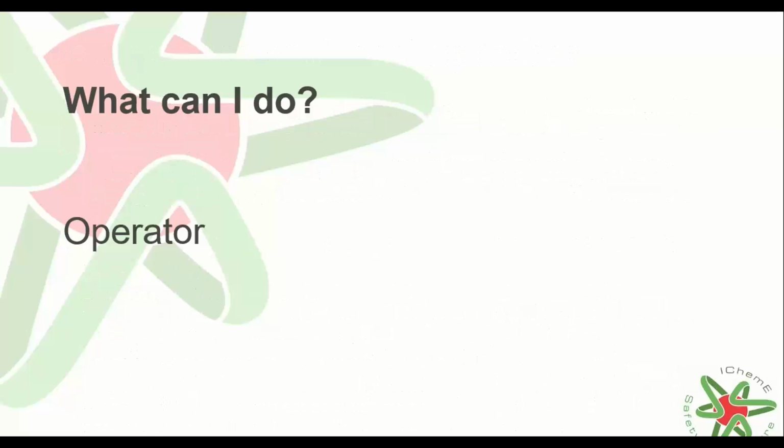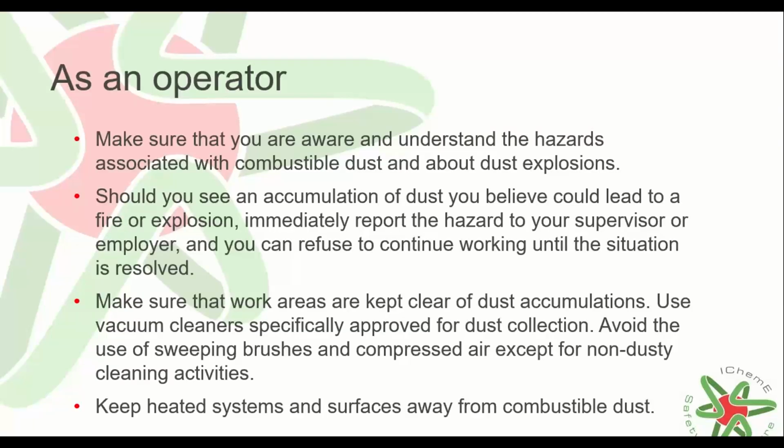I also collected some information about what, as an operator, I can do about dust explosions, and there are a couple of those here. As an operator, make sure that you are aware and understand the hazards associated with combustible dust and dust explosions. And should you see an accumulation of dust that you believe could lead to a fire or explosion, immediately report the hazard to your supervisor or employer, and refuse to continue working until the situation is resolved.